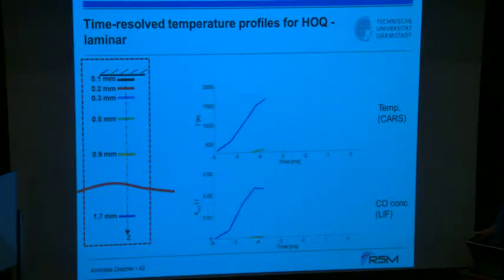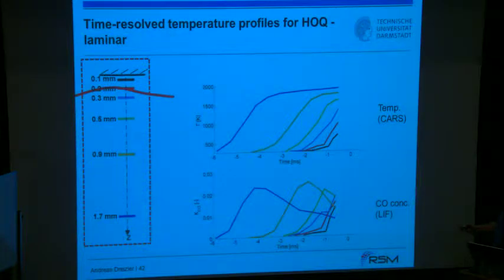So you go further. Now you have here, for this probe sample, at this time, 4 milliseconds prior to extinction, already reached nearly the adiabatic flame temperature on average. Now you reach here this 900 microns position, where now the temperature is sensing the flame as well. CO shoots up, and the same holds true now for those conditions. Now we are very close.